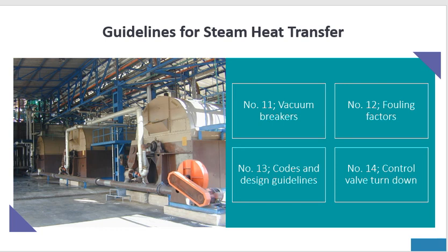14, control valve turndown. The valve maximum flow to minimum tells us the turndown. So in processes, we never hit the maximum, but we always hit the minimum. So we want a control valve that can go to the minimum.